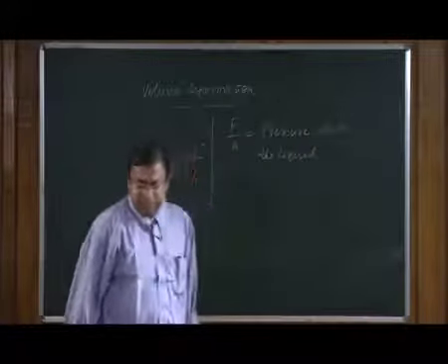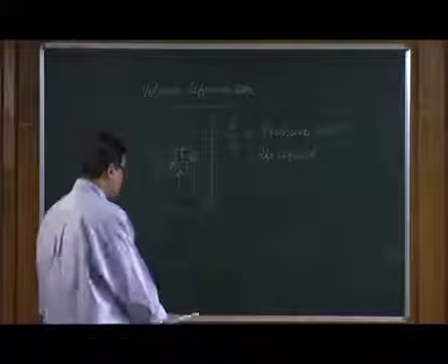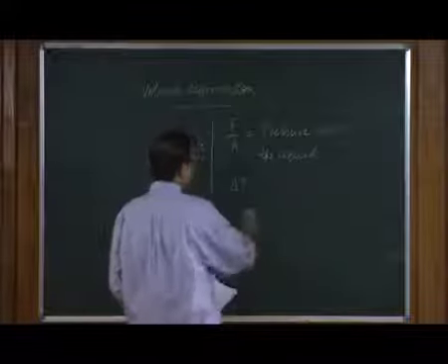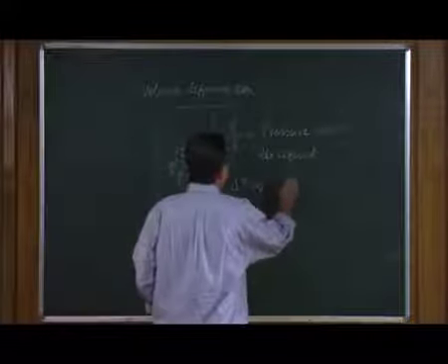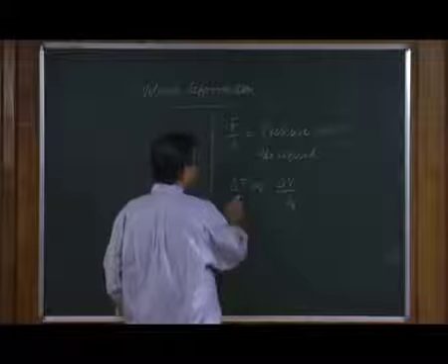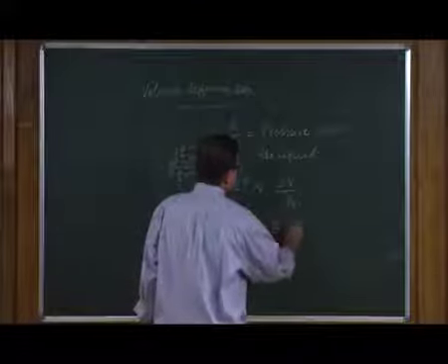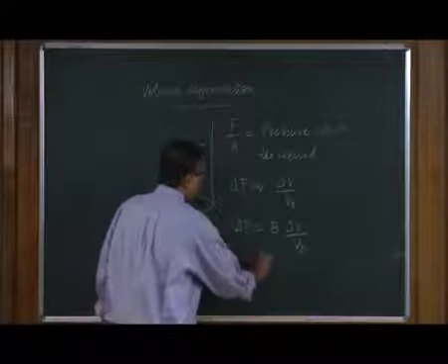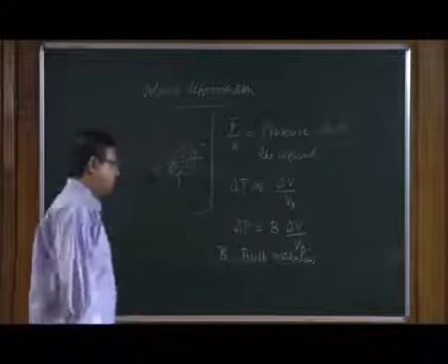So, that tells you that in this particular case, it will cause a deformation to the body, where this pressure, let us call it a change in pressure compared to the original pressure, should be proportional to delta V over V 0, and hence this delta P, which is again the volume stress, can be written as B into delta V by V 0, where B is called the bulk modulus of the system.